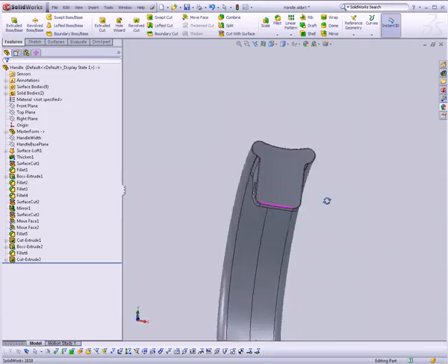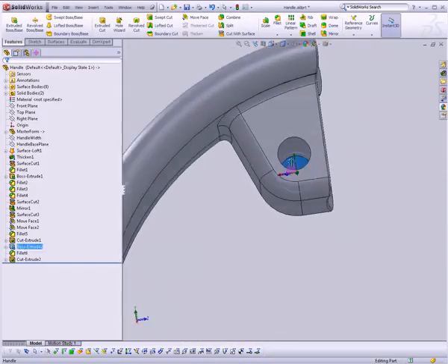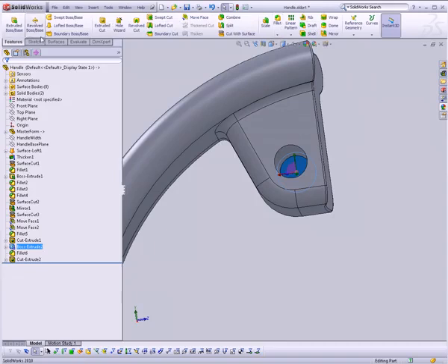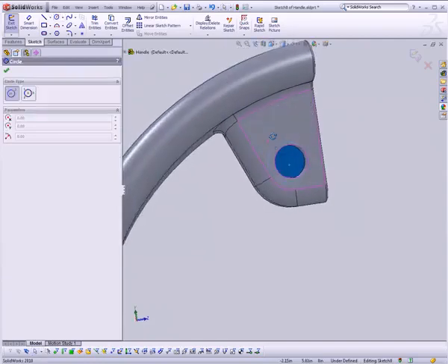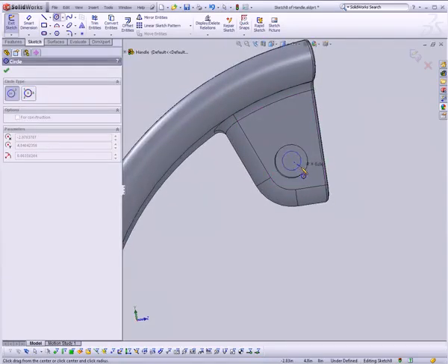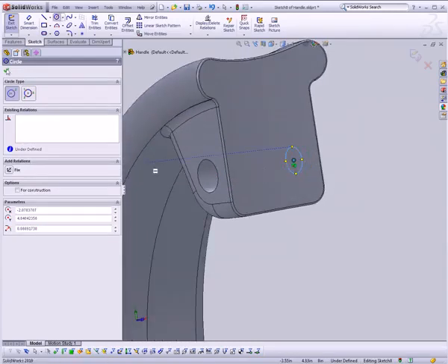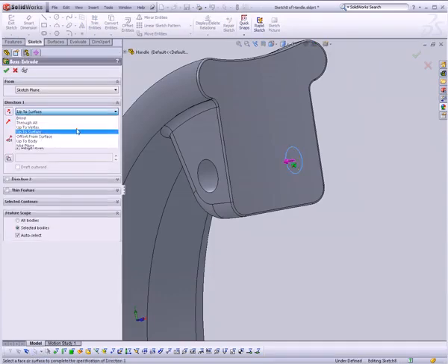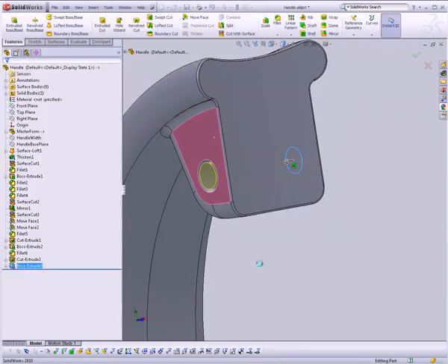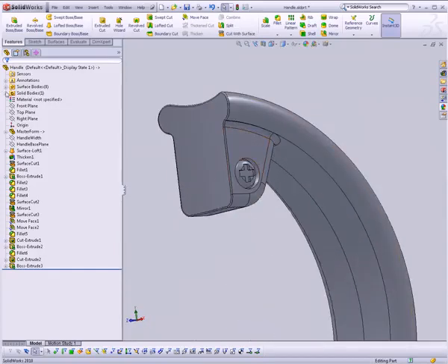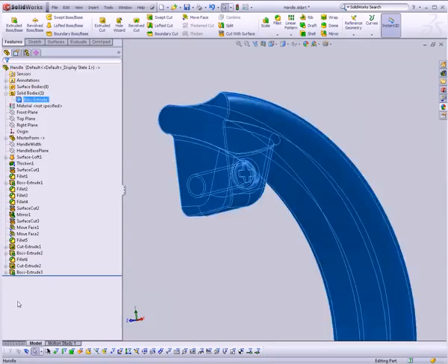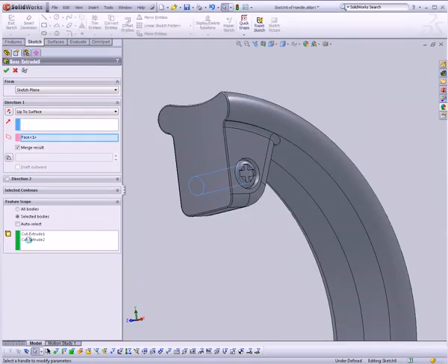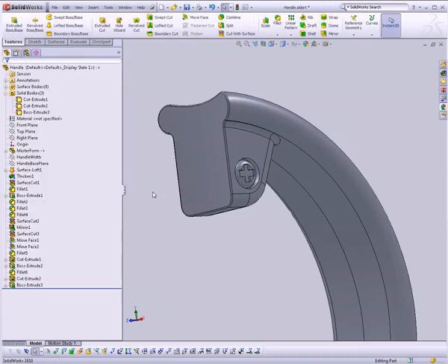We'll just have to put the other side of the screw over here. So we'll do an extruded boss, once again with a circle, back on this back plane, and then bring the extrusion up to surface. Just choose this surface. And that'll work well enough. I think we still have a separate solid body, right? Oh, nope. What'd we do wrong? There we go. That'll work.